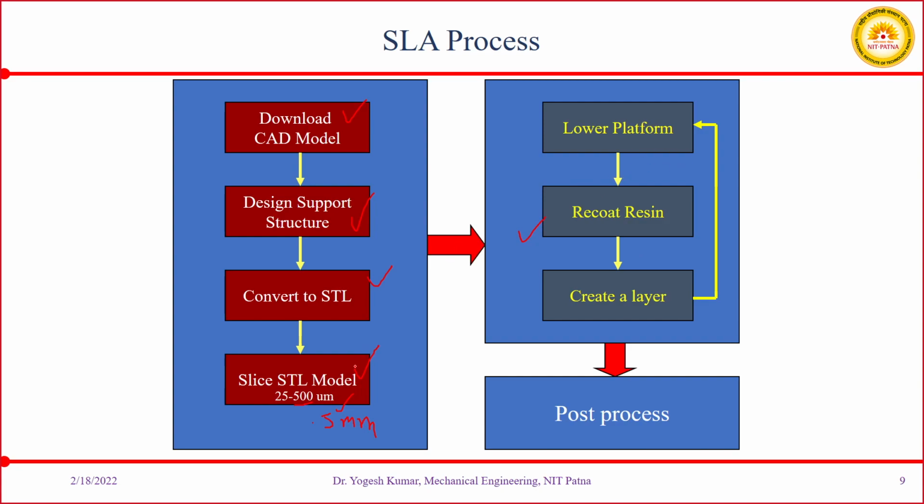So after creation of your slice data, the first thing is that you will spread your liquid resin on your build platform, or you lower the build platform by a height equal to your layer thickness, or the layer height.